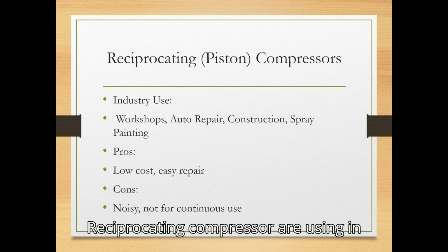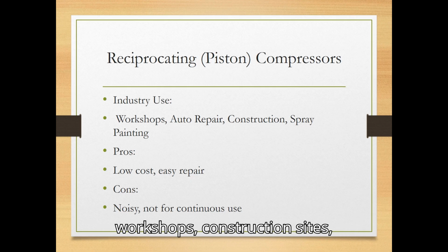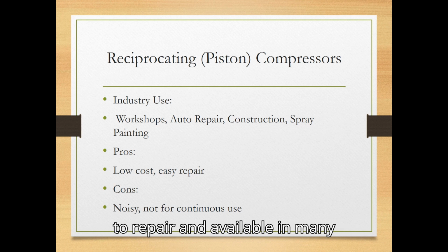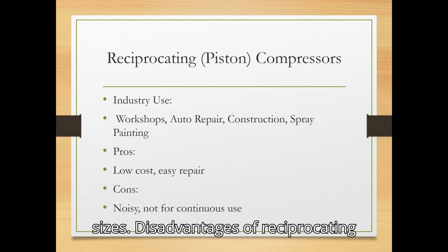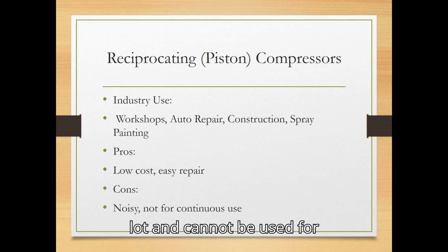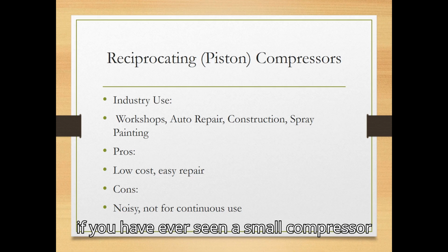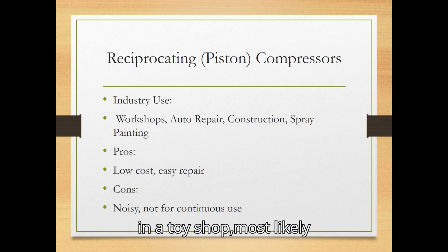Reciprocating compressors are used in workshops, construction sites, garages, and spray painting machines. Advantages of reciprocating air compressors are that they are cheap, easy to repair, and available in many sizes. Disadvantages of reciprocating compressors are that they are noisy, vibrate a lot, and cannot be used for continuous heavy duty operation. So, if you have ever seen a small compressor in a toy shop, most likely it was a piston compressor.